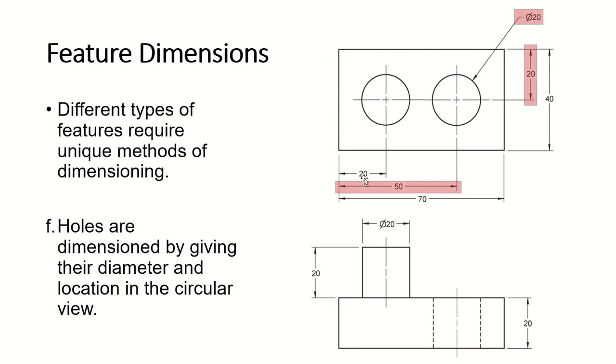I'm doing it with my front view, let's just say, and then I'm going to put all other dimensions to it, from here to here, from there to the first center, second center, and first center. Is this far away? Because this center from that edge is this far away, that center from this edge is that far away. If you subtract it, you're going to get from here to here 30. The same thing from here all the way to the end is 70. So then you know from here to the other end, just subtract, it is 20 again. So 20, 30, and then 20.